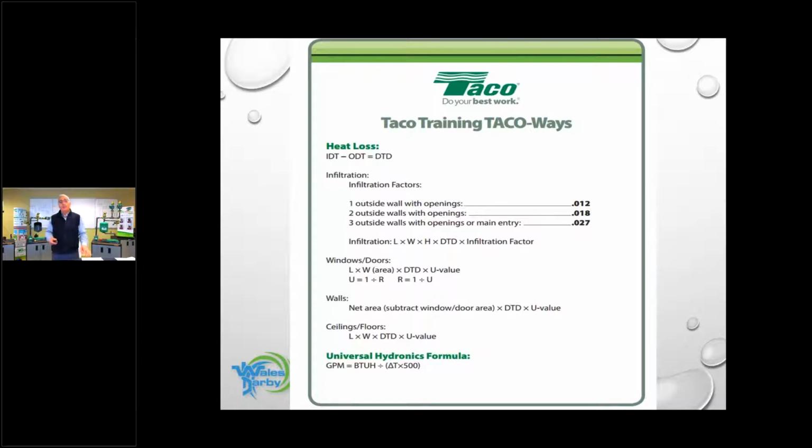So I'm going to take the 30, because it's my 2 3 by 5 windows, times 56 times 0.5, and I will get a BTU of 840. So please make sure you do that math. We got our R value of 1 divided by 2. That got us our 0.5. So then 30 times 56 times 0.5, you should get 840. Write that number down. So now next, we go to the walls.